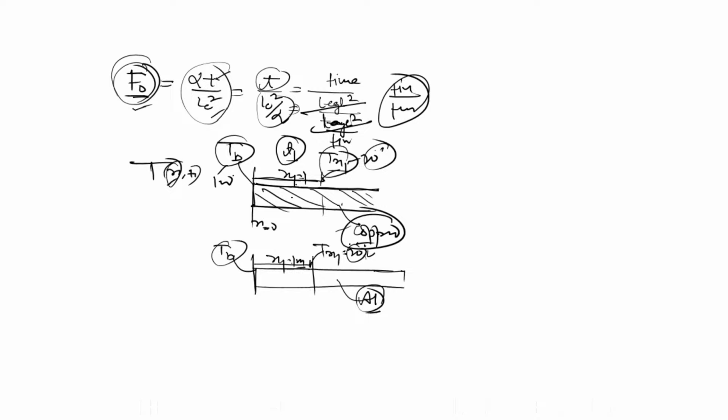It is non-lumped because temperature is going to vary with the space. Yes or no? First tell me, is this a non-lumped as well as unsteady state condition? This is a problem of transient and non-lumped system, because in the lumped system, temperature is uniform with respect to space. Here, temperature is non-uniform. Temperature is going to vary with the space. First of all, non-lumped system.